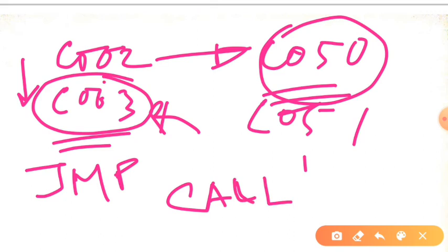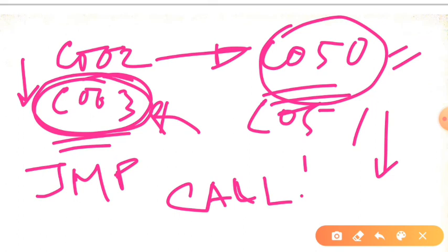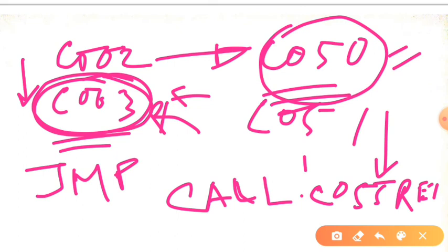it actually saves this next memory address C003. So using the call instruction, if we jump to this particular memory address, and later on we write somewhere, in some memory location, suppose C055, a return instruction, it will come back to the original program sequence, and we can now execute the instructions written from the memory location C003 onwards. So that is the main difference between the call instruction and the jump instruction.